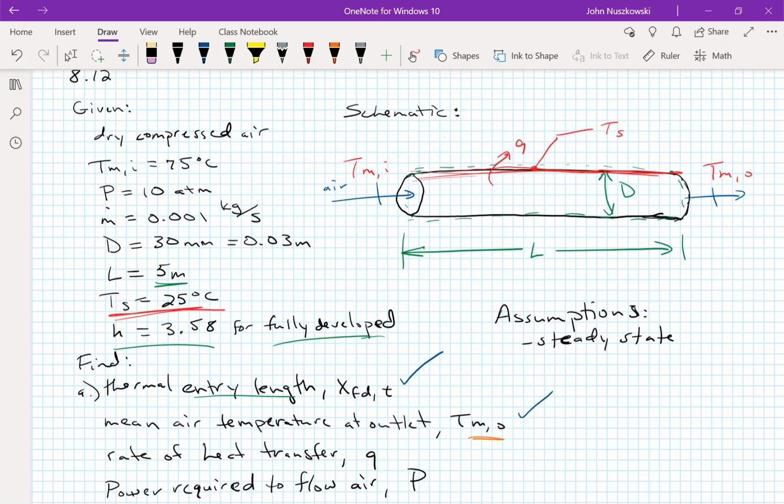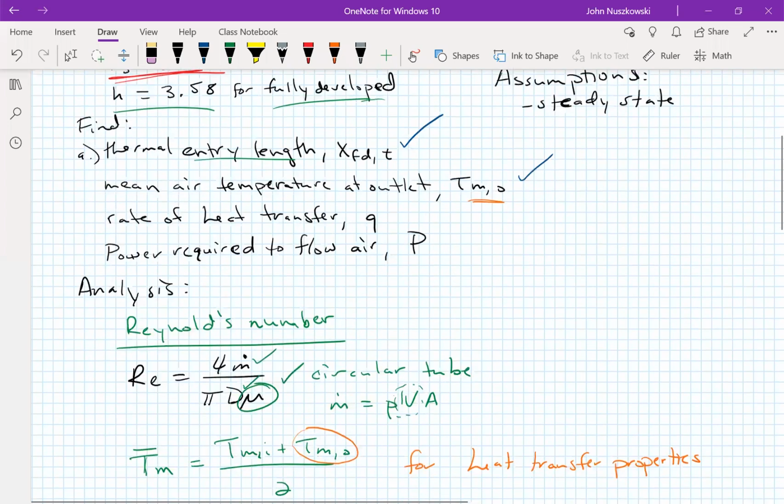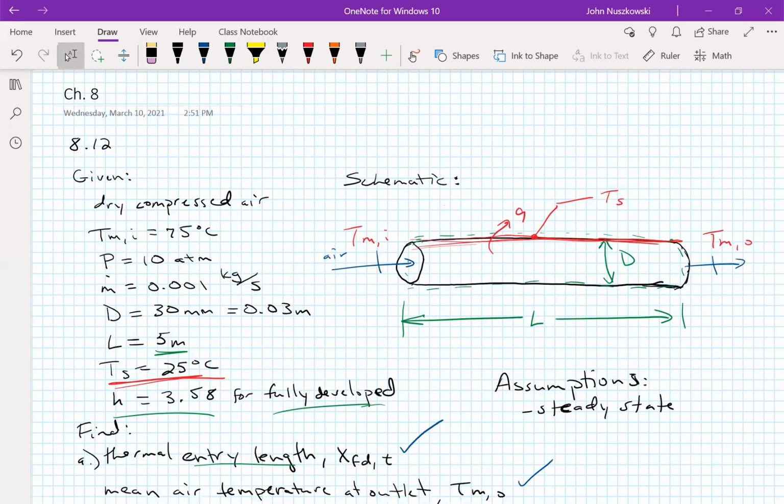Would it be the mass flow rate times specific heat, and the difference of the outlet and inlet temperatures? Yep, and that is really just COE, right? If we're looking at this fluid boundary, we're carrying in enthalpy in, carrying out enthalpy with the mass flow rates, and then we're simplifying enthalpy as Cp times temperature, steady state, neglecting kinetic and potential energy.